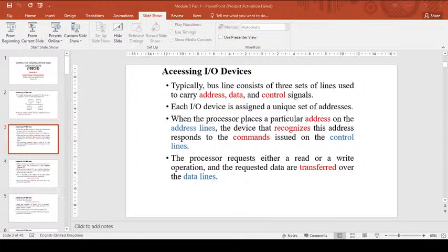That kind of arrangement is called memory mapped IO. So memory will have the addresses which are exclusively used as memory for the computer system, and the remaining address space is used for addressing the input output devices connected to the computer system. Such an arrangement is called memory mapped IO, and you already know how to read and write using a memory mapped IO system, right?